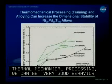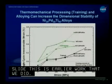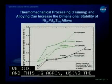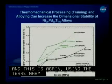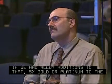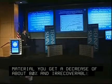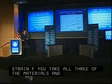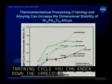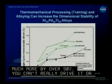This is some earlier work that we did. And this is, again, using the ternary nickel, titanium, palladium alloy as the baseline, the 30 palladium alloy. If we add alloying additions to that, in this case we're adding 5% gold or platinum to the material, you can get a decrease of about 80% in the irrecoverable strain. Now, if you take all three of those materials and mechanically work them, or run them through some kind of a training cycle, you can knock down the irrecoverable strain much more, by over 90%, though in this case we haven't optimized the situation and driven it to zero.